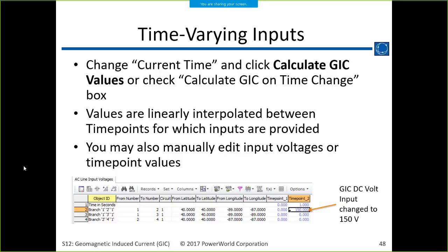I was just thinking, on a large system where there's hundreds of transformers, some of them might be 35 degrees, some of them might be 75 degrees. It'll be varied. Exactly. There is no one thing to choose, but you could be overly conservative and just grab the maximum for them all.